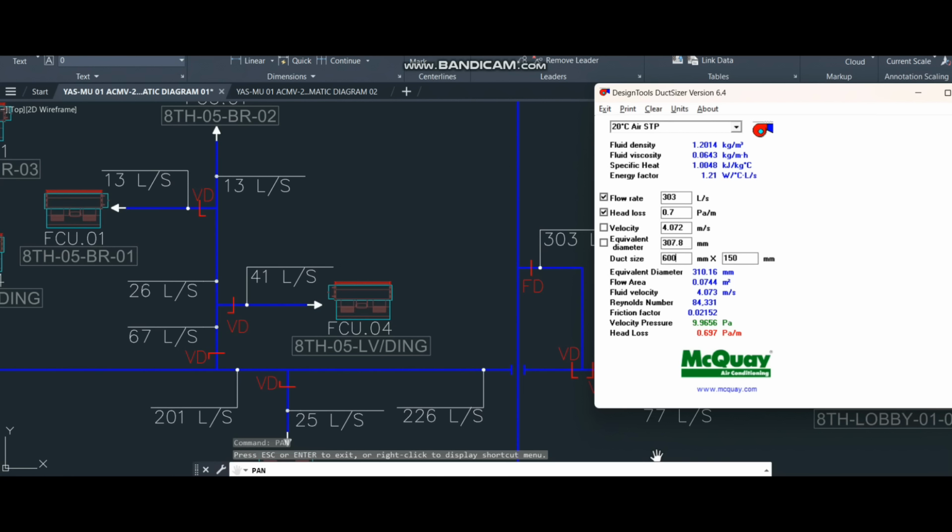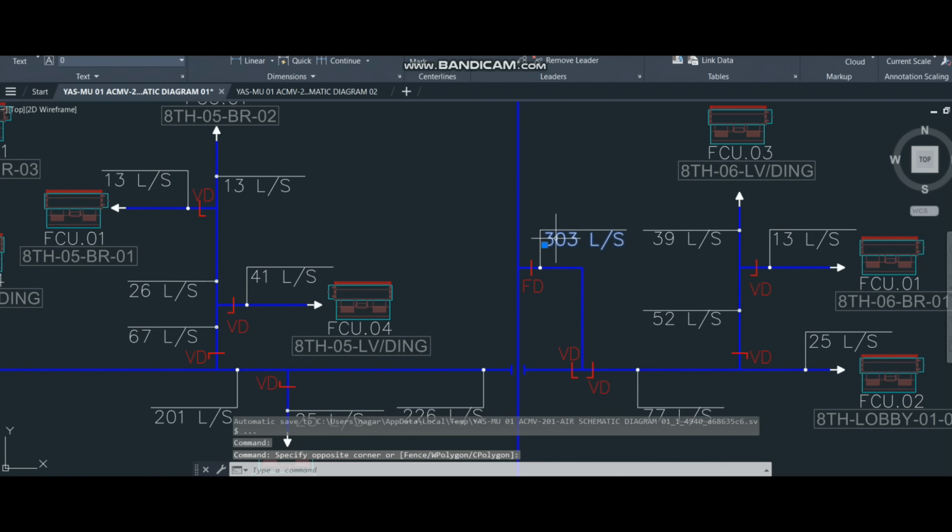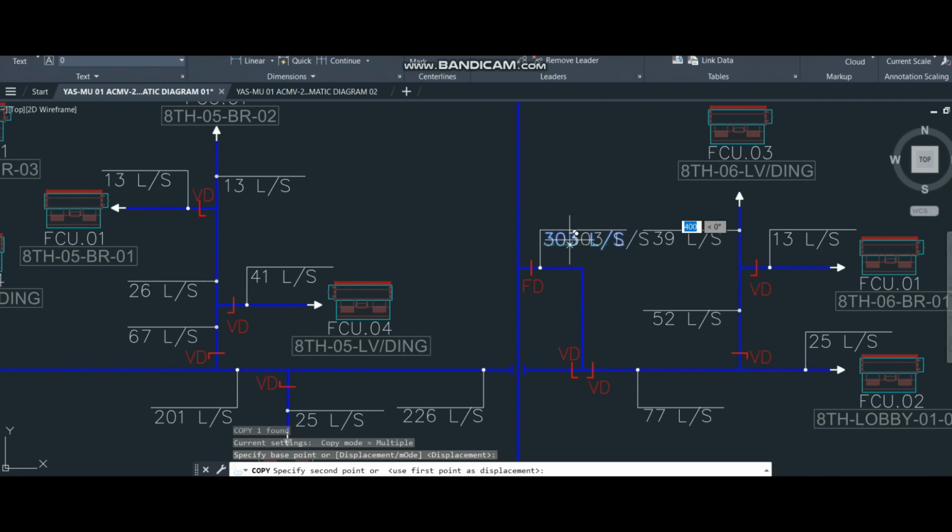And the duct size I will convert to 300 by 300, or you can go with 400 by 200. This is as per your wish based on the site condition, and make sure the aspect ratio is falling within the limit. So I will follow the duct design here, 400 by 200, what I got from our duct design.